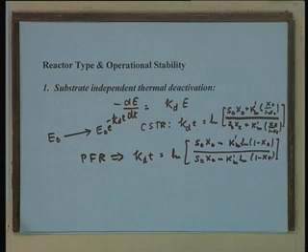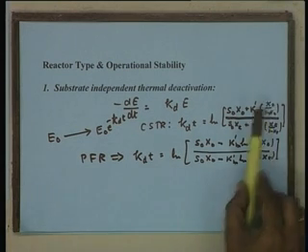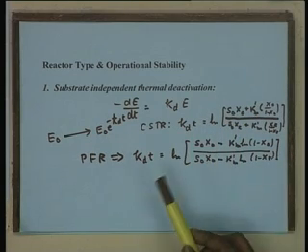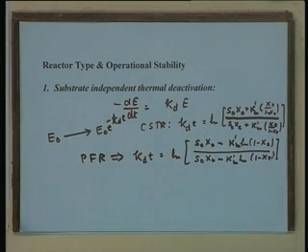Whereas if we are operating in the first order regime, the first term will be neglected, and then the difference in conversion decay rates between PFR and CSTR will be magnified. The xt value in the two cases after the elapse of time t will be different, and the output of the plug flow reactor will decrease much faster with time than in the case of a CSTR.